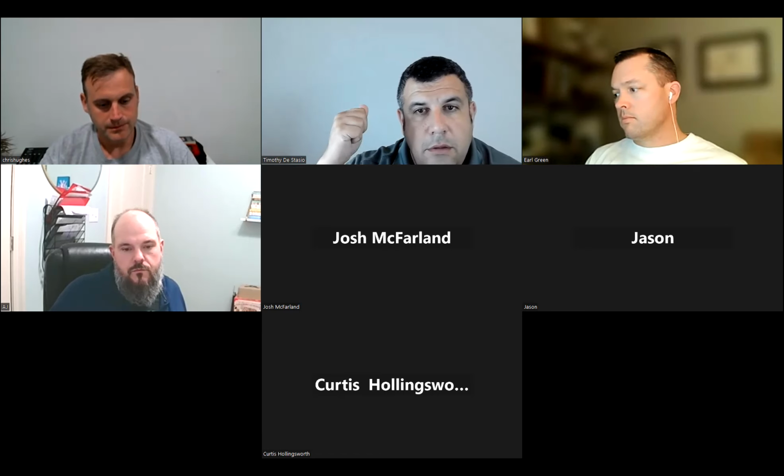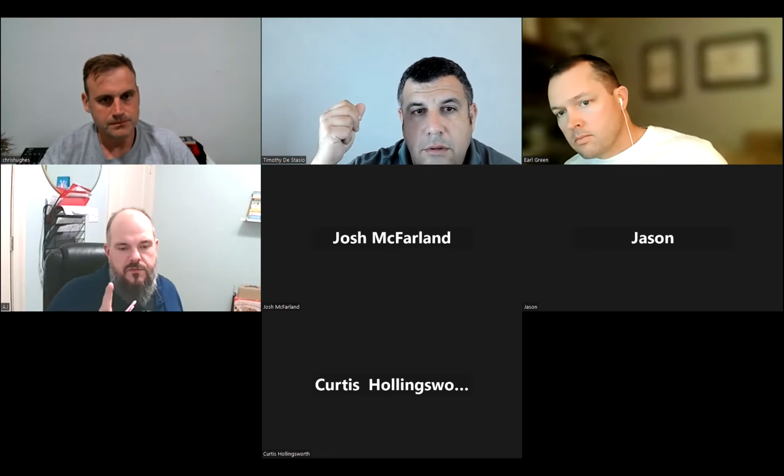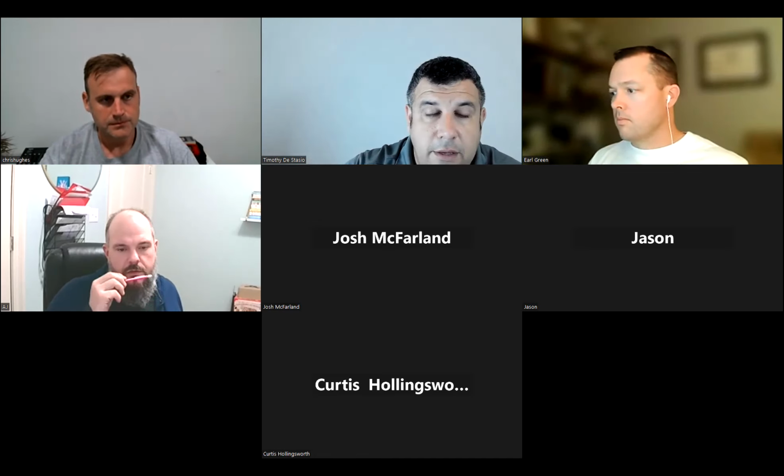On my comfort consults, and I'd be interested to see what y'all's approach is, I include a load calculation, the blower door test, and a MeasureQuick. I'm going to do the load calc on the house, see what the unit's actually doing, and quantify infiltration. You do this on your first visit? Well, I sell it. It's a service where I make enough money that it's worth it to me. I'm not giving it away.